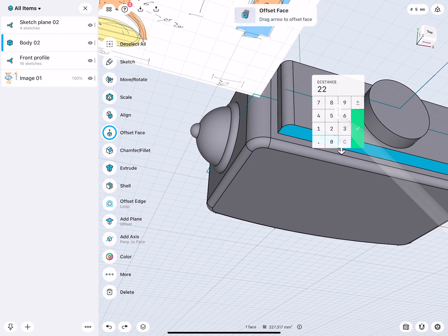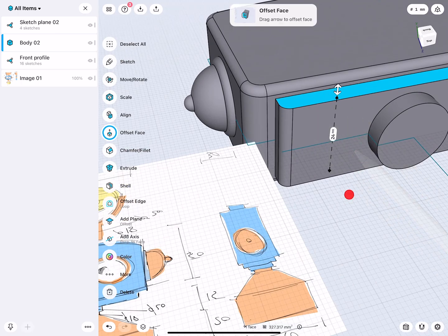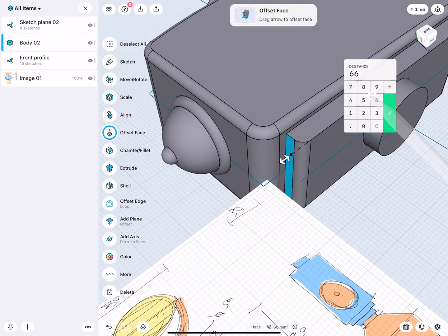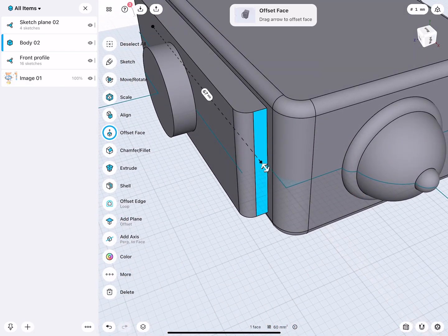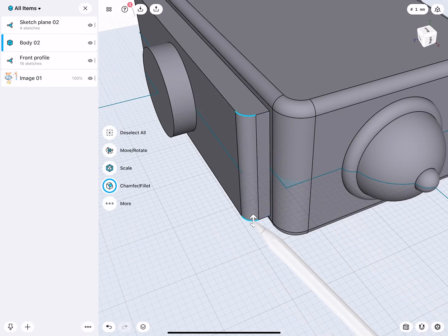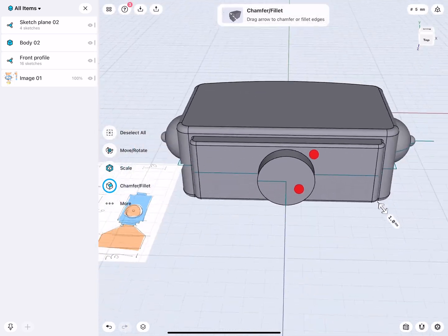Super easy. Let's make this wider. 23. Okay. 24. So you see, I'm just pushing this over 1mm each side. And the fillet actually moves with it. There. And now I can go ahead and round these corners easily. And there I have enough flash. Pretty cool.